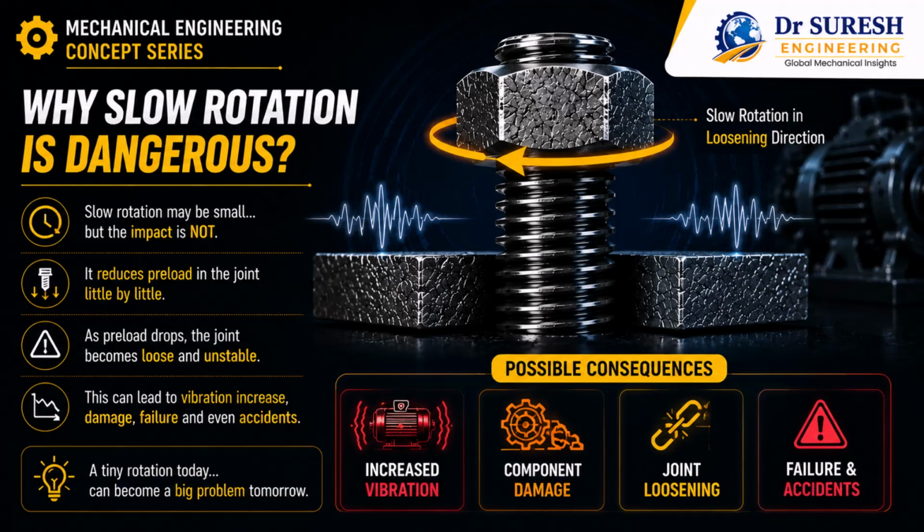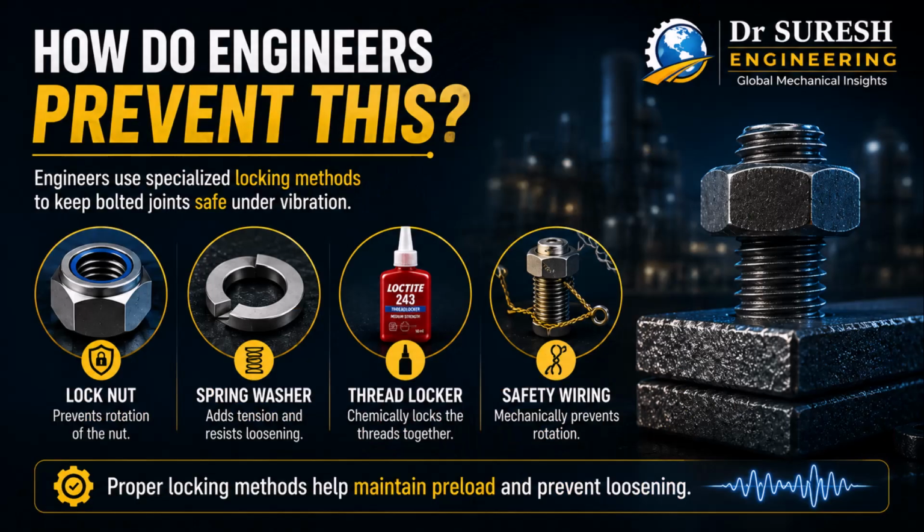As this condition continues, the machine may experience increased vibration, component damage, joint failure, and in critical systems, even serious accidents. A tiny rotation today can become a major mechanical failure tomorrow. But engineers do not simply tighten bolts and hope they remain secure. In real mechanical systems, especially under vibration, specialized locking methods are used to prevent loosening.